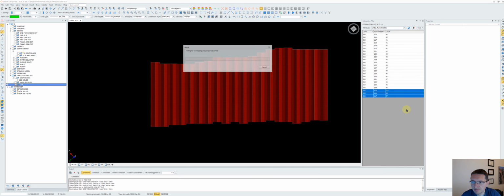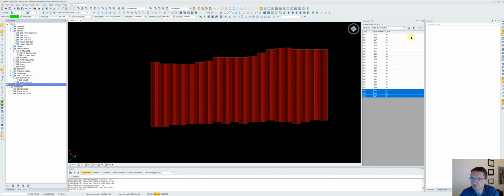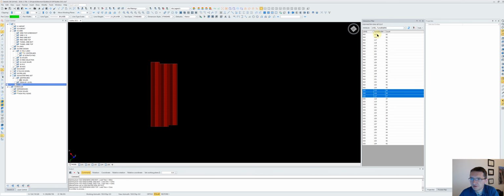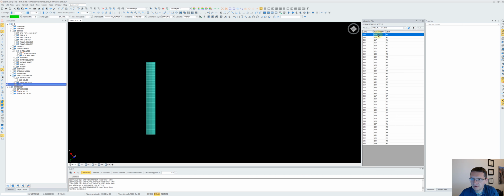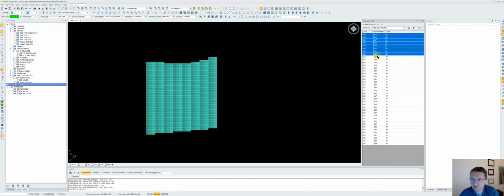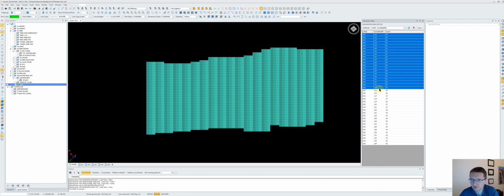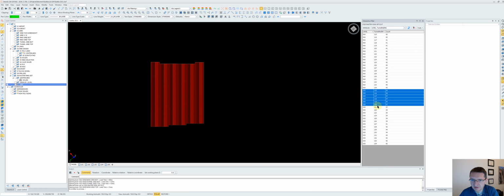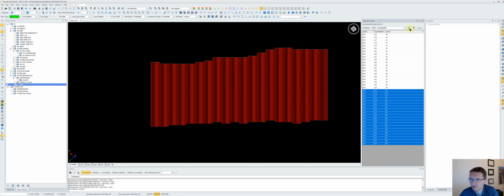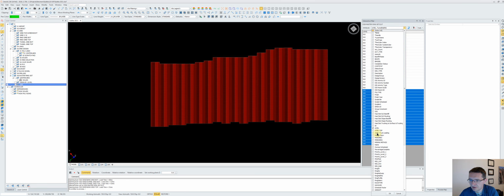And let's hit OK. So I'm using these grids to populate the tunnel number and the ring number. So now, yeah, 15, 16, 17, 18, 19, 20. That one goes all the way through. Then we got 15, 16, 17. Yep, that one goes all the way through. So the tunnel numbers are working correctly.